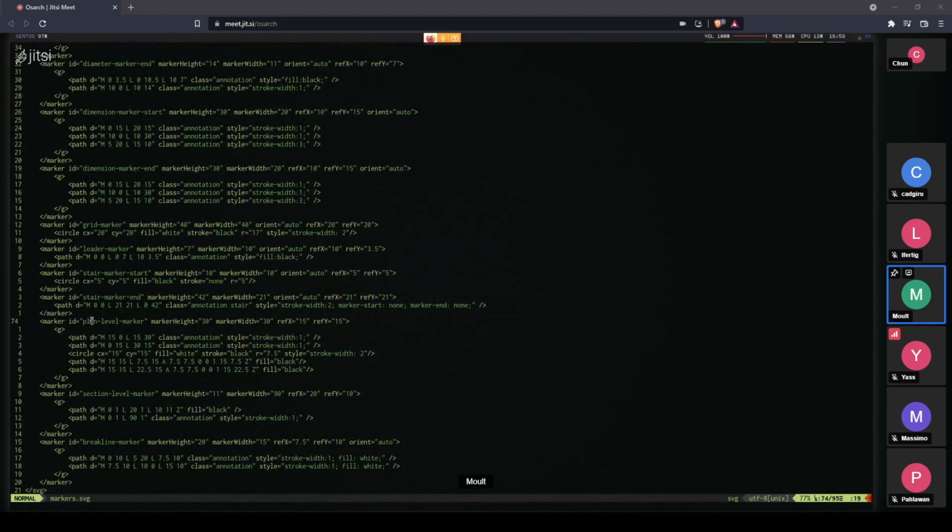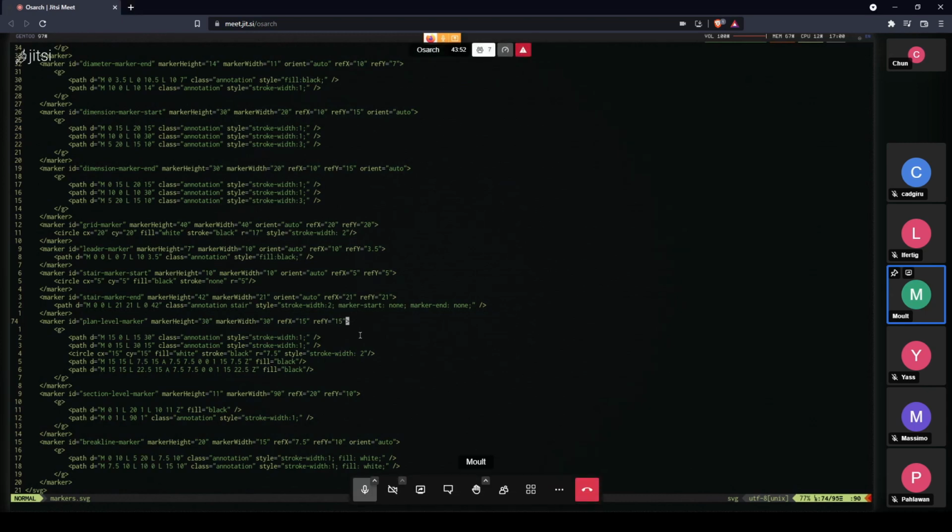You can have your own style, and you can edit this with Inkscape. All of these are just Inkscape paths. So you can just draw a shape and copy the path code into here and give it a name. And just the convention is that it's all in millimeters. So this stair marker has a circle of a radius of 5 millimeters.